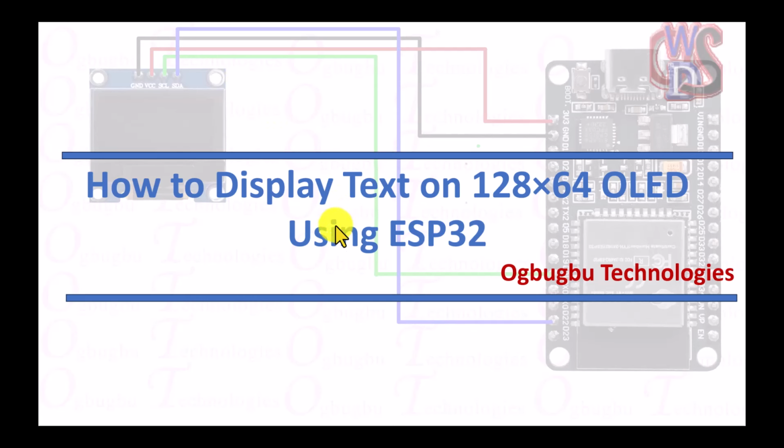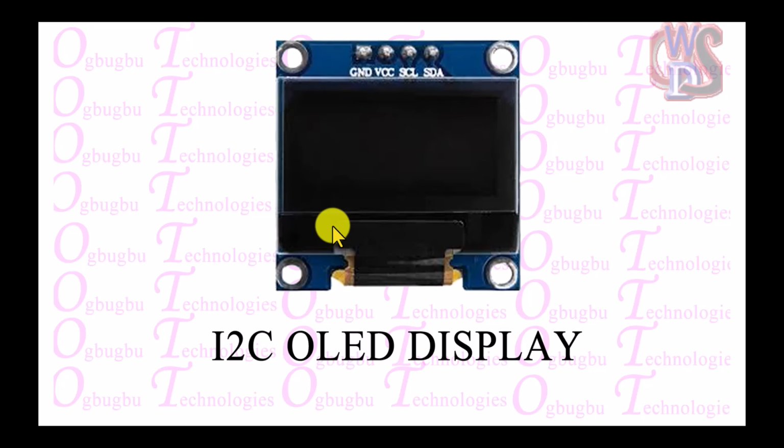So for the requirements, we're going to be needing an ESP32 dev board, which you're already seeing on the screen, and we'll be needing an I2C OLED display. Basically, as you can see, this I2C technology gives us the ability to use just two wires to pass signals. Here is your ground, VCC, serial clock, serial data. Now all this screen needs is just these four cables, two for power, two for data transmission. Now these are the two basic components we need for this tutorial to go on.